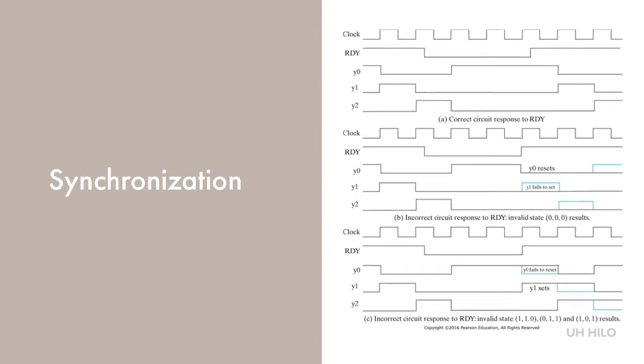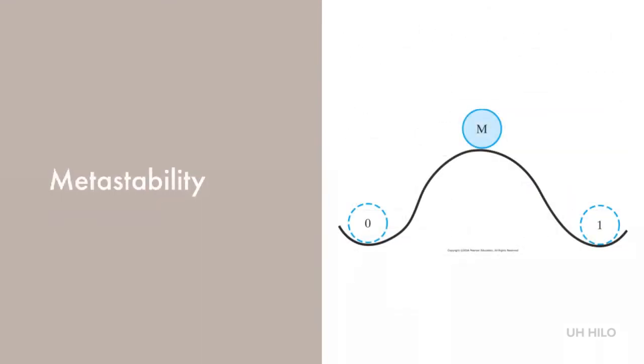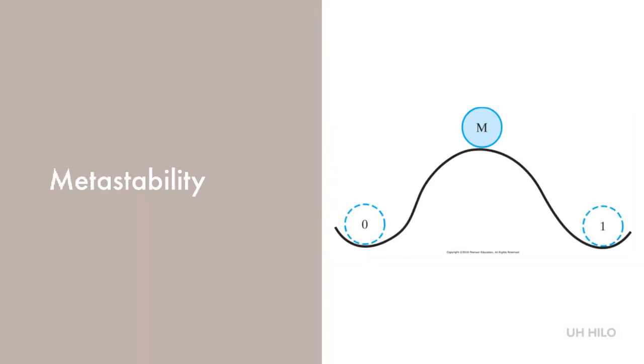Latches are used to construct flip-flops, and they have three potential states: stable 1, stable 0, and metastable. When an input to a cross-coupled pair of latch gates changes at just the right timing relationship with the clock edge, a narrow pulse can be generated. The pulse may just have enough energy to change the latch state to a metastable point, where both gates have equal output values with voltages between 1 and 0. Like the mechanical system, the latch, and hence the flip-flop containing it, will eventually go to 0 or 1. However, the length of time it remains in the metastable state is non-deterministic.